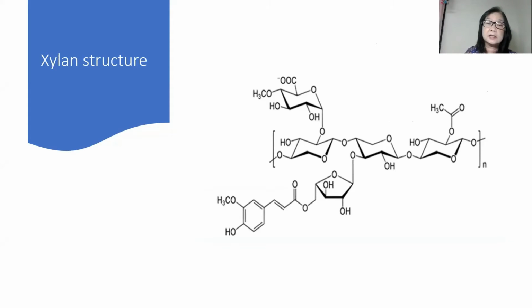So that's why I said xylanase is very useful and can help reduce chlorine use in the bleaching process, because it can cut the chain here. You see the existence of xylanase can cut all this chain, so the chlorine can easily penetrate the pulp structure. So that's why we don't need a lot of chlorine, because xylanase has already cut all these very complex chains.